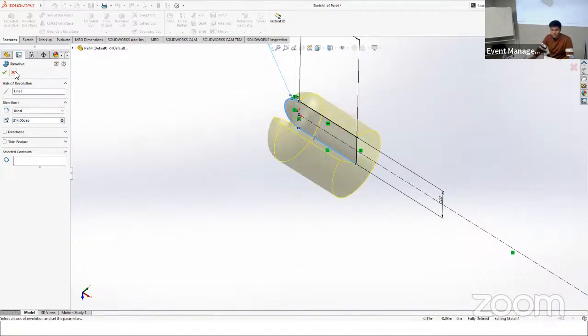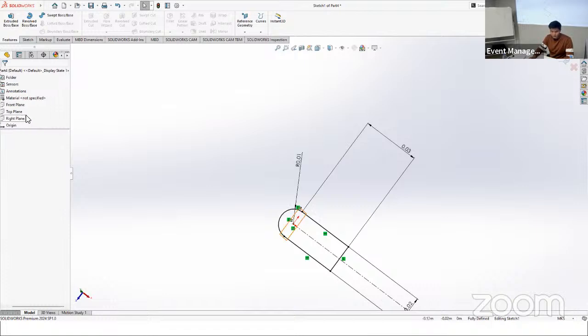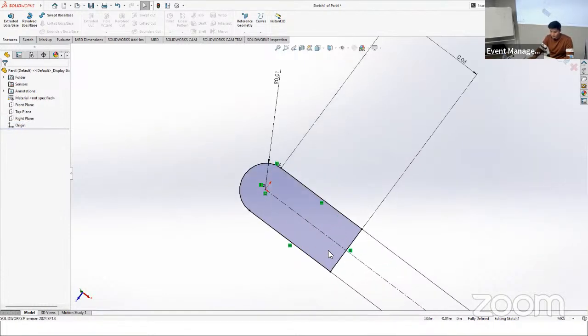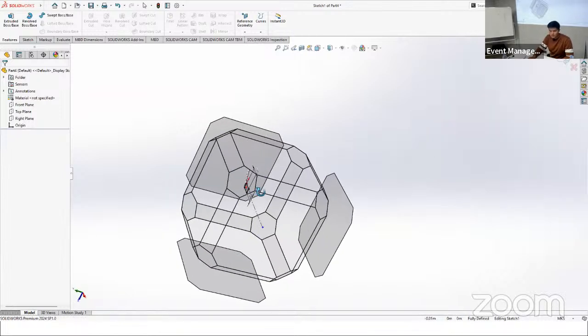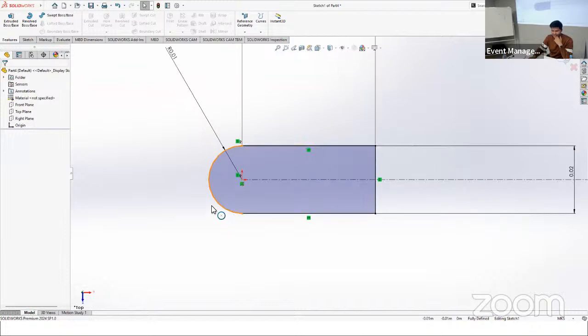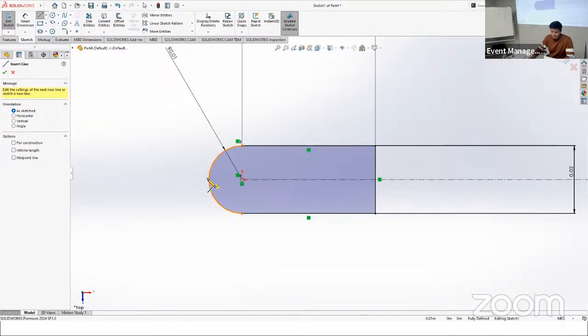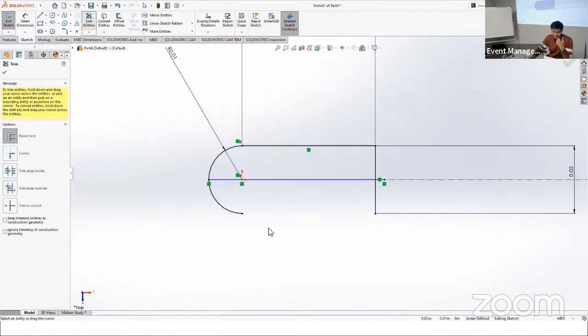Oh, okay. It actually does not like revolving around itself, so we should make it half of that. So let's begin. Let's again open our sketch and use View Normal To, that's the tool for viewing, so we can choose the right angle. It seems very unpleasant for your eyes because in the 3D modeling world, there's no top, down, right, left. There's no gravity, so it will go around if I mess with the mouse the wrong way. So let's divide that part into 2, and we take trim entities and trim half of it.